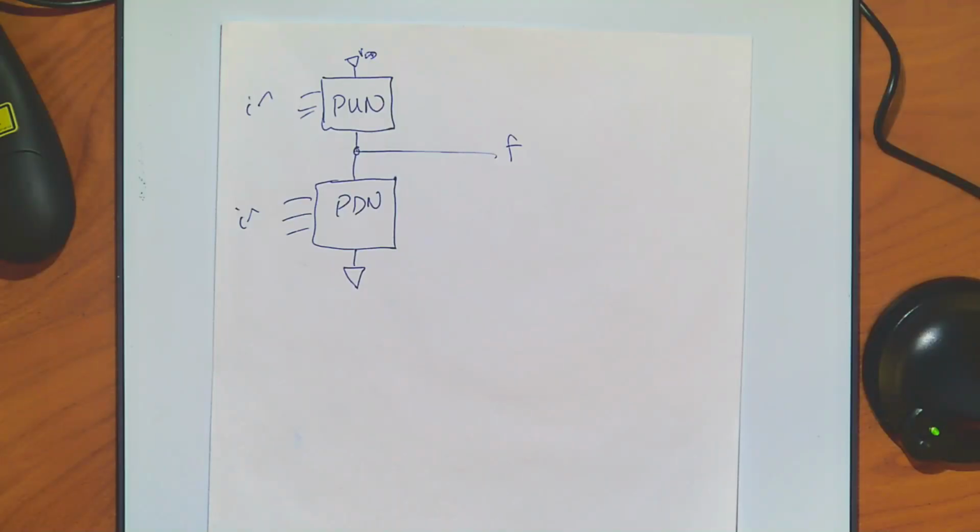So we're going to talk about two different major categories today. One is going to be another static design technique called transmission gates. And basically the idea of a transmission gate is they're really good in certain cases. It's designed to just be a very elegant way, particularly to do muxes. But it's basically kind of like a nice analog switch that we can then turn into logic.